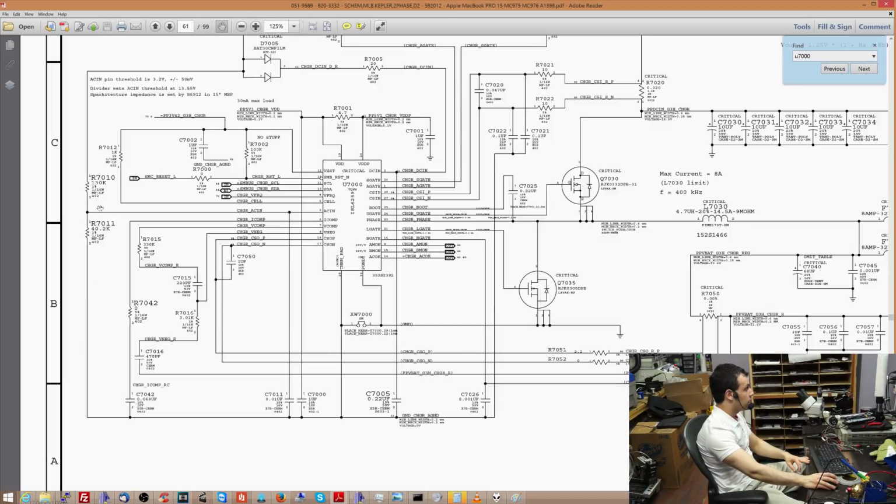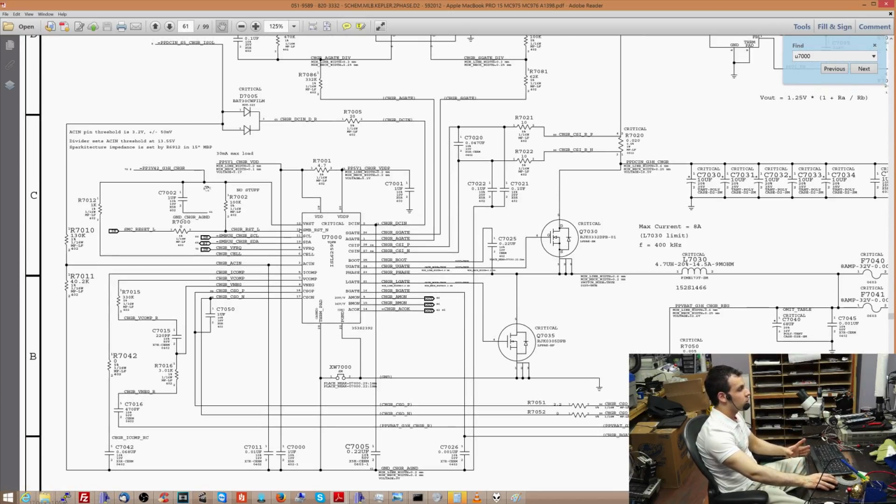So let's say this 130 kilo ohm and this 40 kilo ohm resistor both became 0 ohms because they got wet, or because of a power surge, or because somebody hit it or punctured it. Now this would send the power all the way to ground. So any one of these components, when they malfunction, can start to function like a wire. So you have all these components that are going to ground and taking voltages to ground for different reasons to accomplish different things, but you don't want it to be like a wire going to ground.